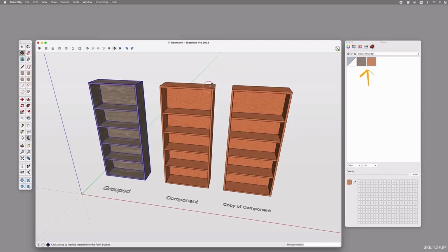You can observe how the material selection changes as I use the pipette tool. Now let's modify the gray material in this wooden texture. On a Mac, you will need to double-click on the icon to open the Edit options, while on Windows, there is an additional tab labeled Edit.